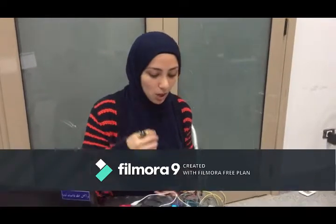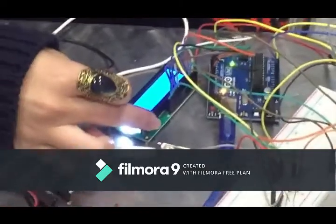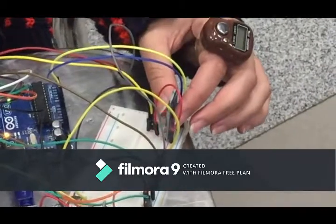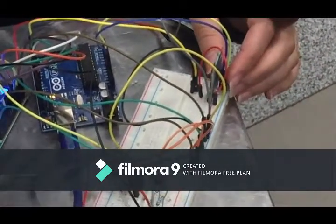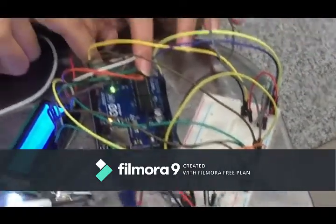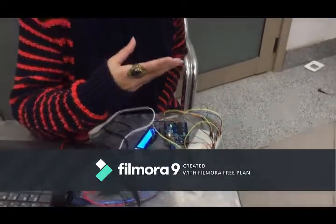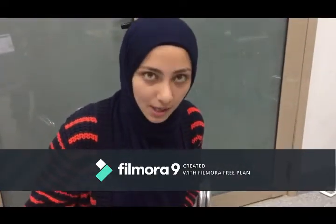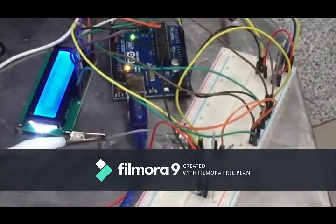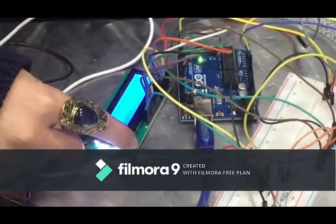As for the hardware, we used an LCD in order to display the characters or the text converted. We also used the Bluetooth module in order to connect the Android device, which uses the MIT app for the conversion, to the Arduino board. And once the conversion is done using the MIT app from voice to text, the text is displayed on the LCD. We used a potentiometer in order to adjust the brightness or the light intensity of the LCD.